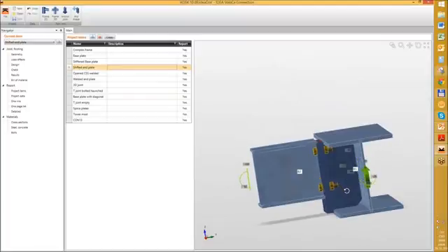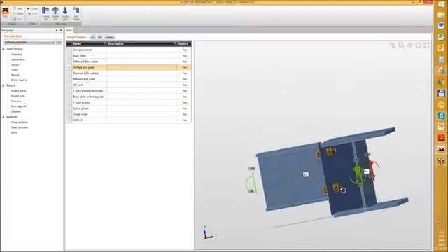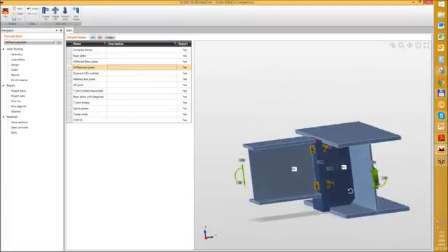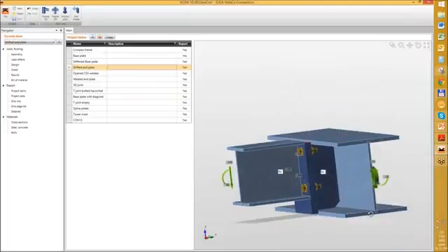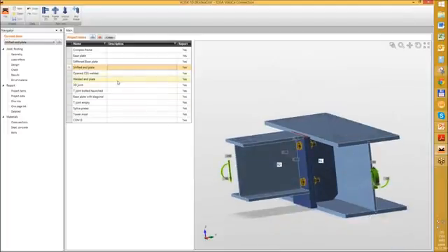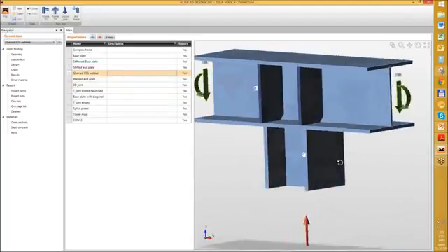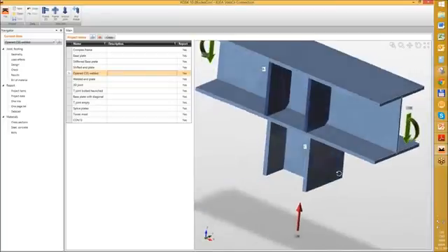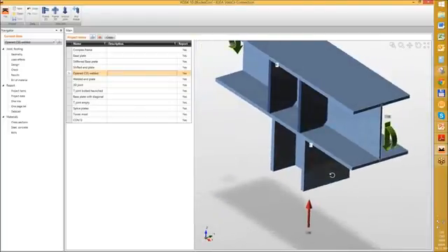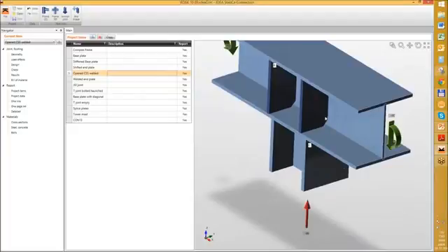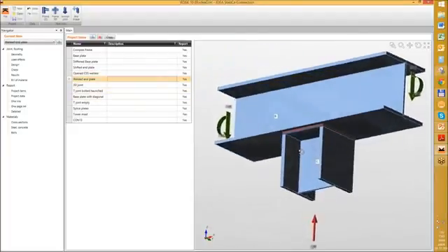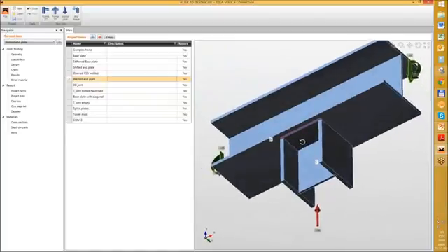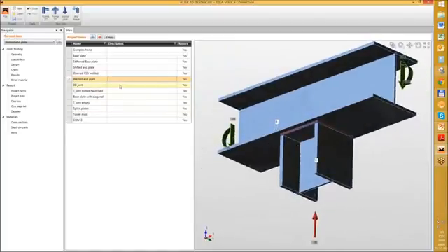These shifted end plates are quite interesting for connections with bending moment on the weak axis of another beam. We can make welded joints from open sections. We can do such things like end plates which are welded.